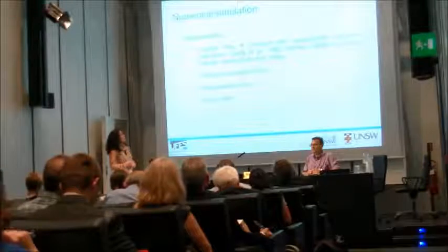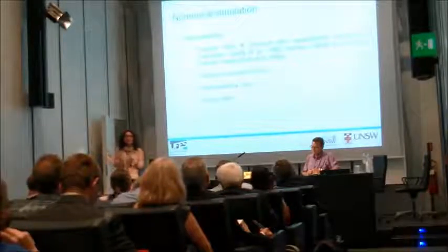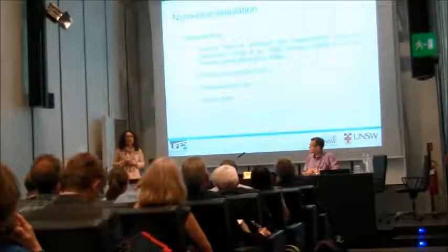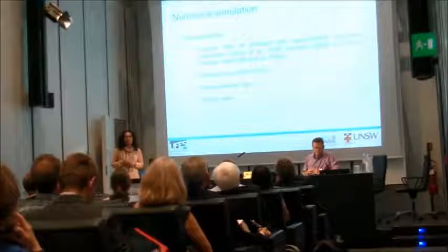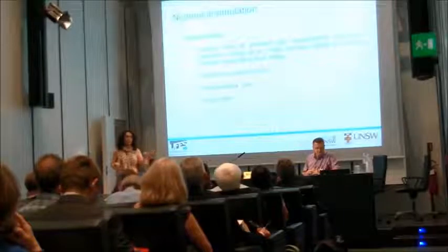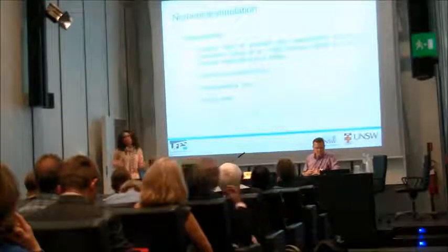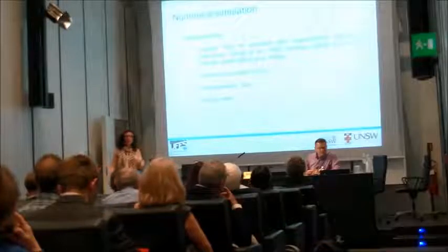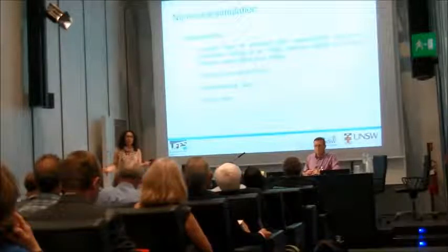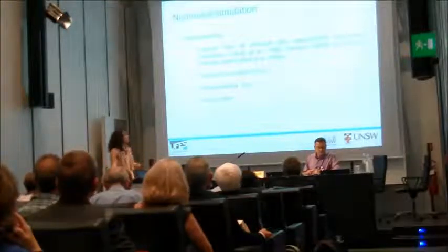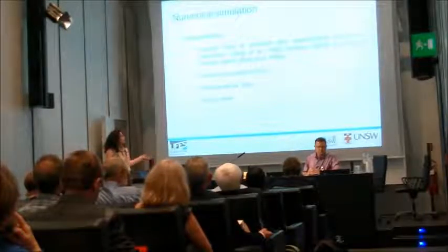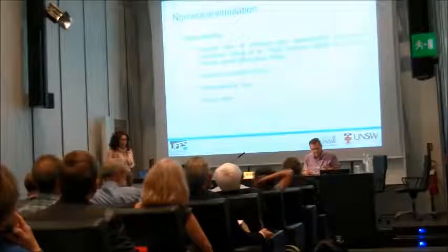We assume that the flow is laminar. It's a bit tricky because the Reynolds number is in the transitional regime. We could decrease or increase the velocity to be really sure it was laminar or to be really sure it's turbulent. There's a little bit of a problem simulating turbulent flows, but we can do it as well. We assume an isothermal condition, the flow is incompressible, and we also assumed a steady-state regime.